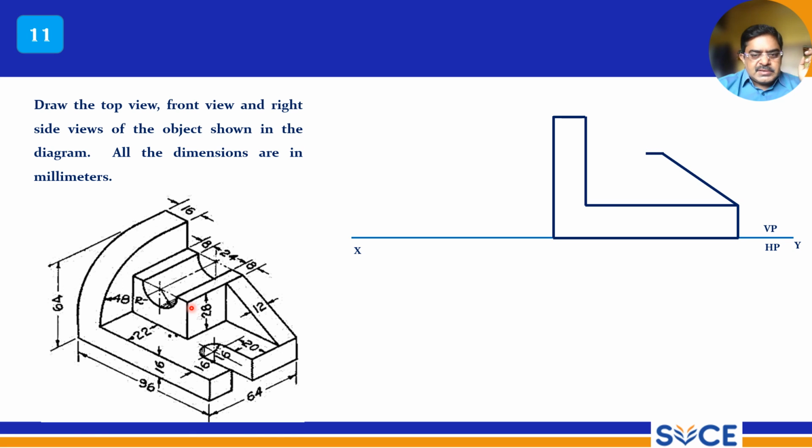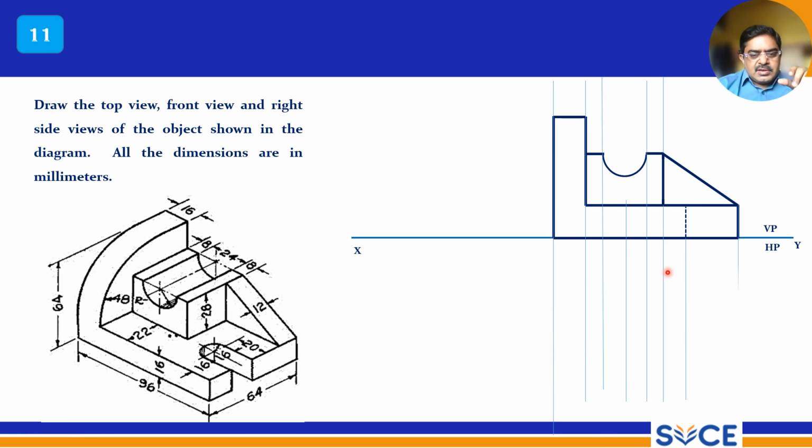And this is the horizontal, right? This line now, this line, and then with the given radius, that is 8 mm, right? 24 mm diameter, right? 12 mm radius, you draw a semicircle, and draw a horizontal line. So now there is a keyhole, and that is invisible, right? So draw that edge, and then draw the top view.